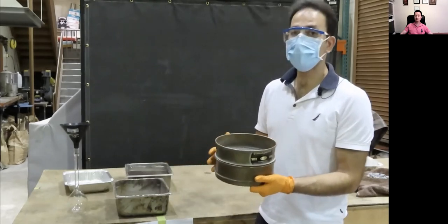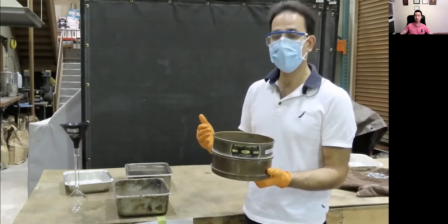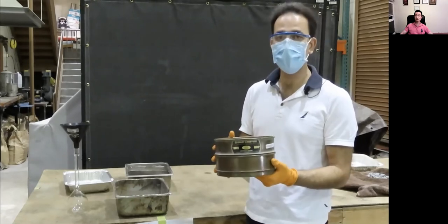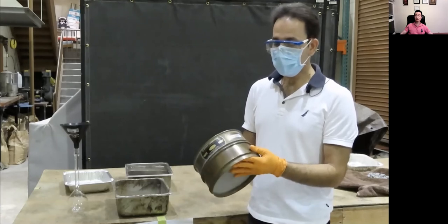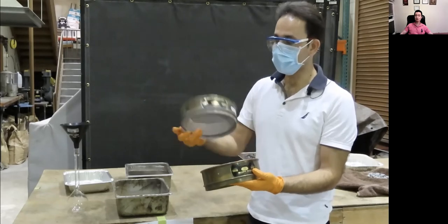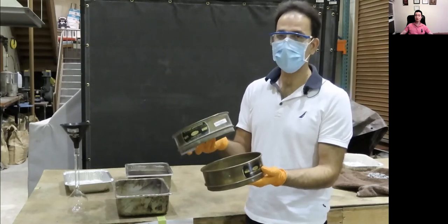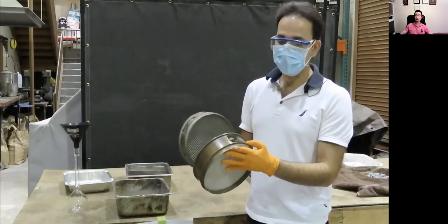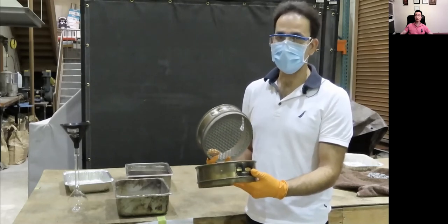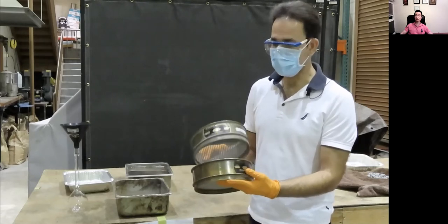I have a strategy to drain the fine aggregate first because it's going to take me a lot of time to drain the fine aggregate and then dry the surface. I'm going to show you with a hair dryer. So I can use two sieves, sieve number 100 underneath and sieve number 4, because I don't want any particles larger than sieve number 4, the reason why I use this. And I'm going to use sieve number 100 to drain the water as much as possible. And also I don't need any particles finer than sieve number 100.